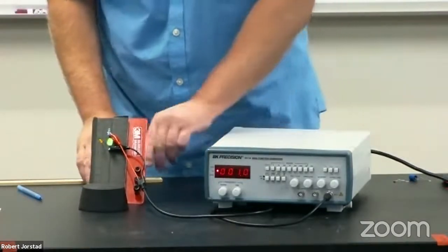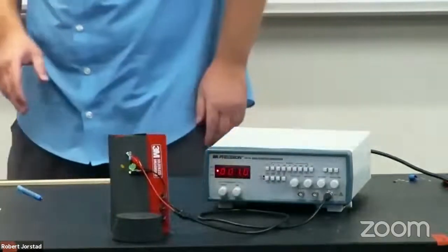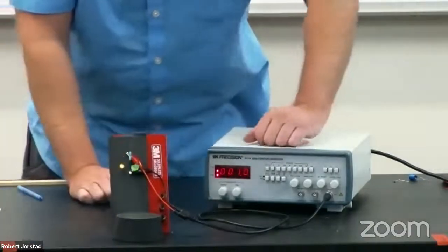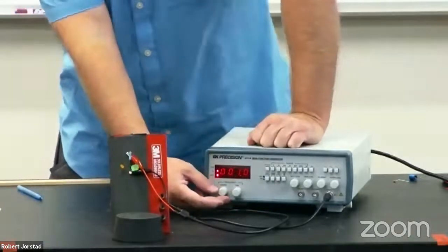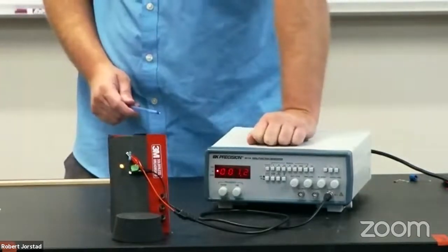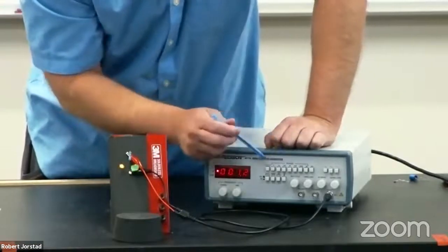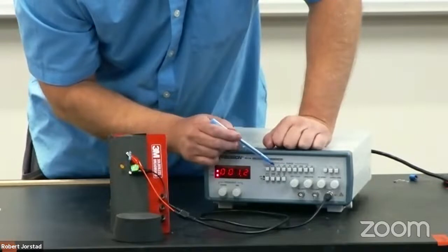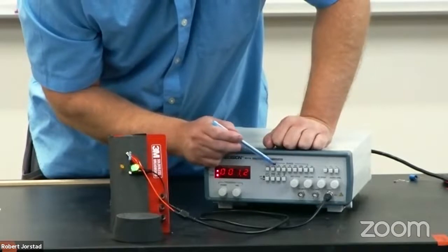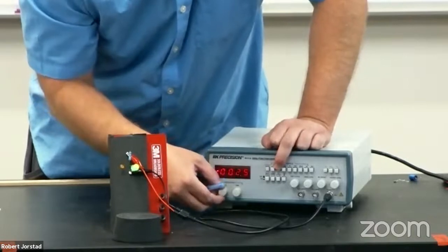But now I'm going to try and gradually speed this up. And I'm going to scoot this as far forward as I can just so you can get as good a view as possible. Okay, I'm going to spread these out a little bit. Watch what happens as I increase the frequency. We see it blinking more rapidly now, right? And now I can explain how this works later, but I'm going to dramatically increase the frequency by pressing these buttons. The idea here is this button goes up to 5 hertz. This one goes up to 50. So basically I'm changing the decade, so to speak. So this should be 10 times faster right here.